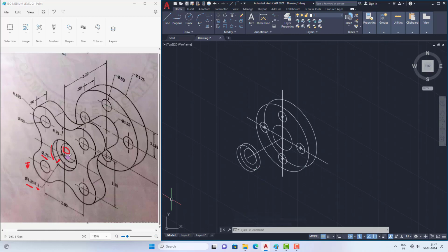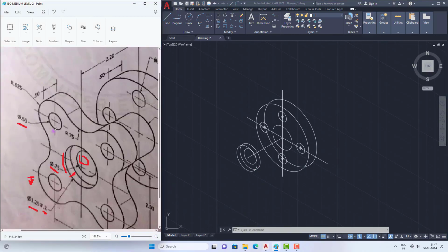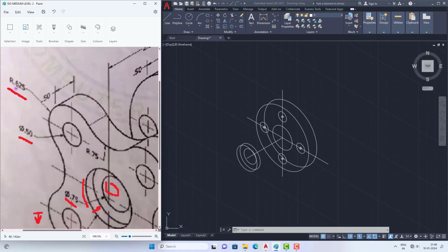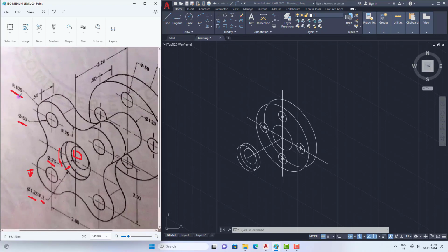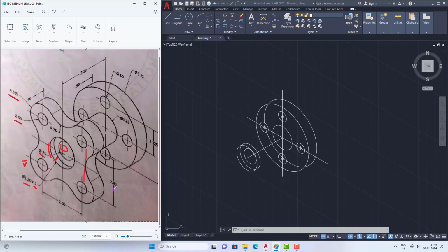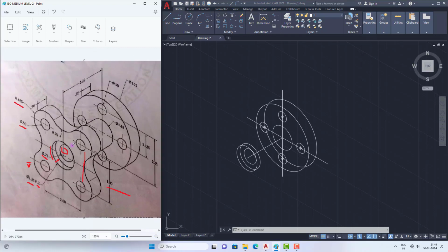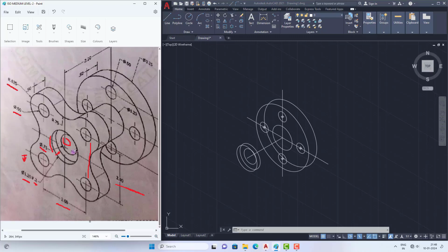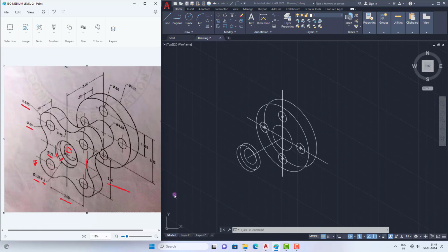Now I got a profile like this. Now what should I do? So there are circles here, see, there are circles, which are of diameter 0.50. There are 4 small circles here, and the outer circle has given here 0.625, which is of radius 0.625, but those are at some location. So the center points of these 2 circles are given here, which is 2.00, and the same, so the center point is given here horizontally, 2.00. So horizontal and vertical. So firstly we need to draw that.